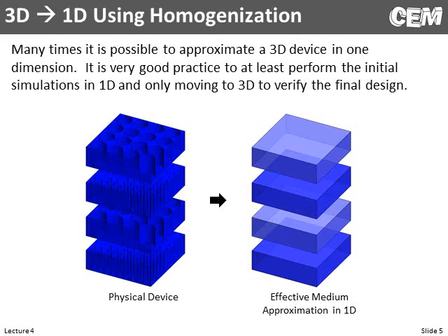If we make the holes smaller, there's more dielectric here, and that probably has a higher dielectric constant. And now we can think of this 3D complex thing as a stack of these homogeneous layers, just with alternating dielectric. Great place to start. We may have to follow it up with this once we get our design close and do it real simply. Then this is a much more complex simulation to do.